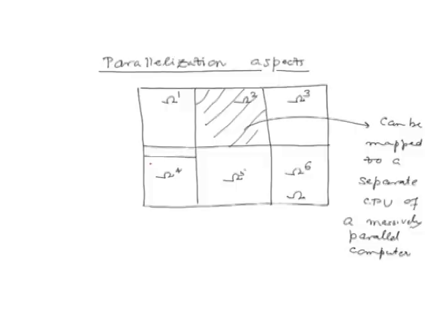So, we do not have to make use of any advanced or fairly complicated mesh partitioning algorithms in this case. We can simply decompose a problem domain into small subdomains. We can have different types of Cartesian grids or grids of different density on each subdomain, and the interface information can be easily passed on from one processor to another as a part of the solution process. Yet another important aspect which is permitted by this finite difference and domain decomposition based approach is,